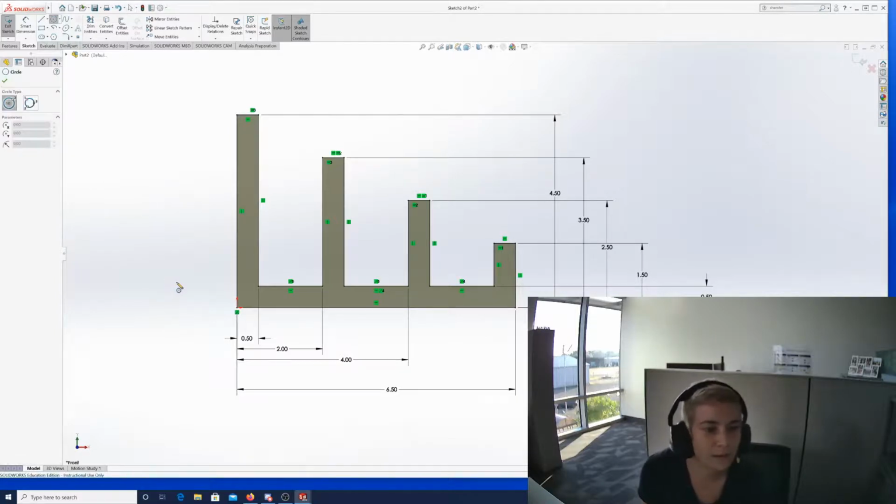One thing that I think you might have questions about, especially after working on this week's exercise, is how do I make a hole in my sketch? Say I have a solid shape and then I draw a circle on top of it. It's going to look like a circle on top of a square, like you just layered different shapes on each other. How do I make a hole that goes through the sketch? If you draw a circle on top of your other shape, it's not going to just sit on top of it.